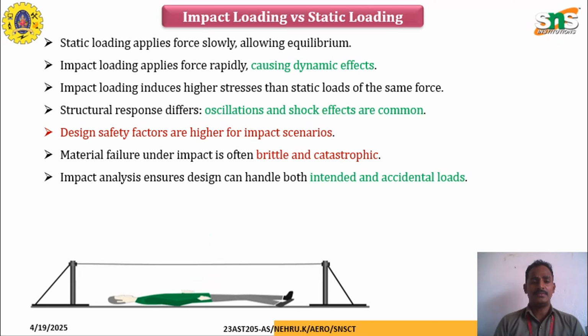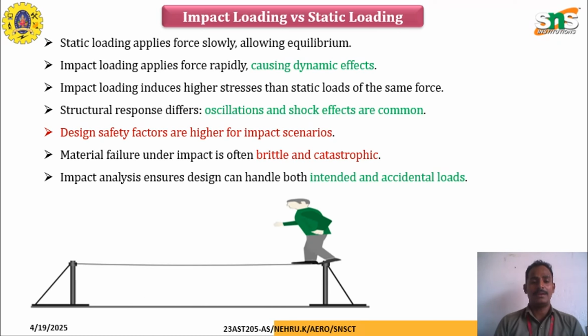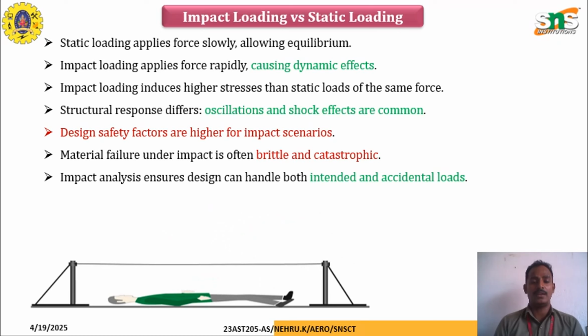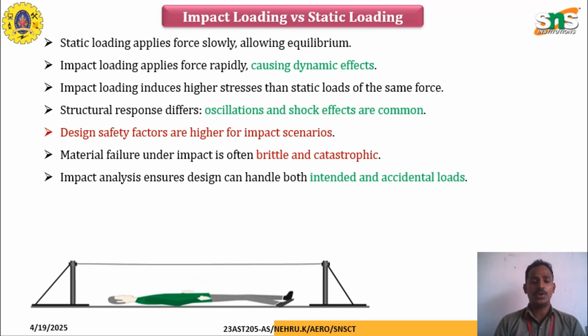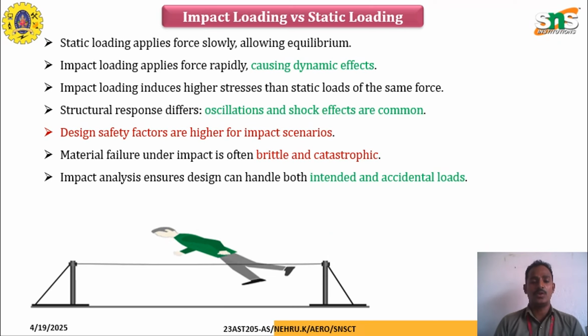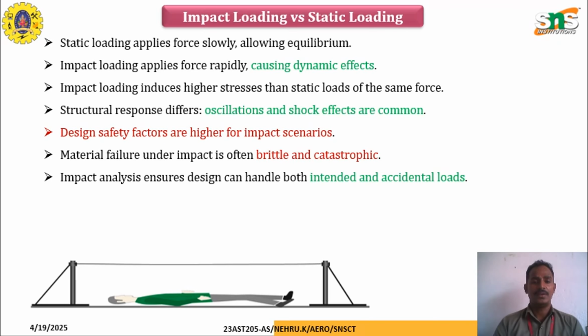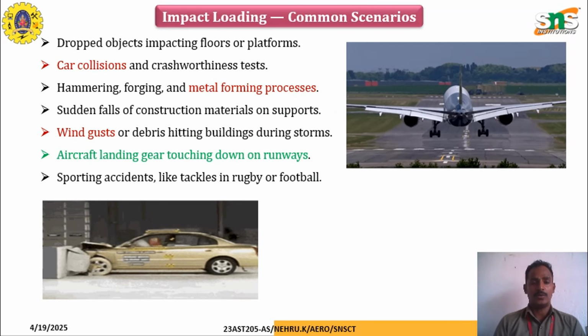The design safety factors are higher for the impact scenario, because the material under impact often fails in a brittle or catastrophic way. Impact analysis ensures the design can handle both intended and accidental loads. These are a few examples of impact and static load.